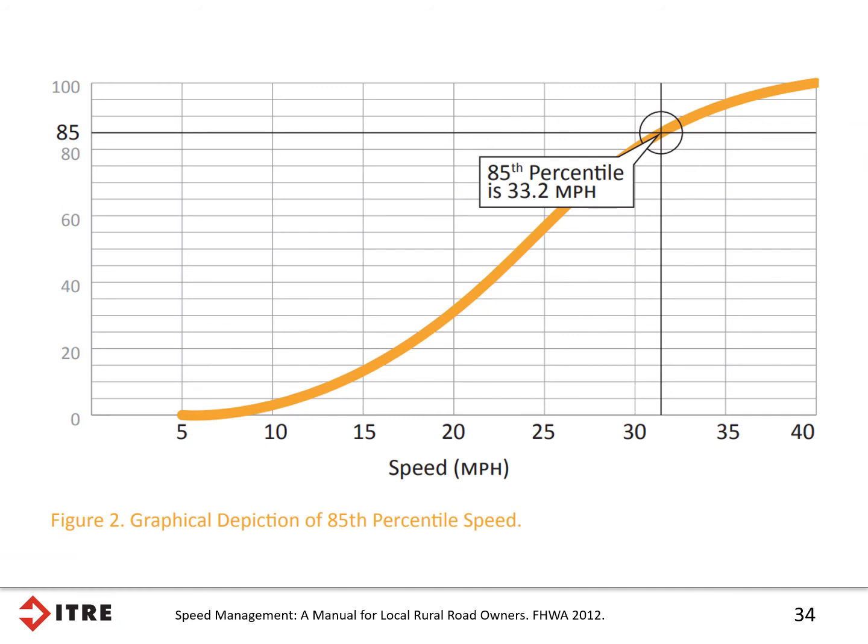Something that comes up a lot, and I want to go ahead and establish what it is: the 85th percentile speed. This is a fairly misunderstood and often misused piece of information, but it is important to understand vehicle speeds. When we look at speed studies and assess current vehicle speeds, 85th percentile speed is one that's used, and again, it is an important piece of information that can influence the ultimate speed limit that is selected.